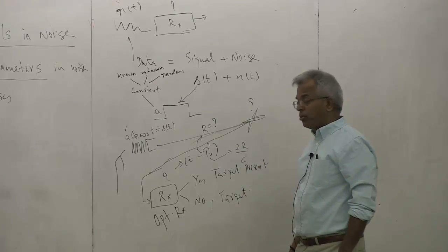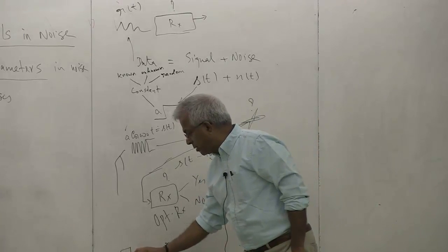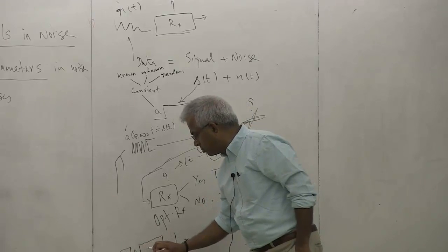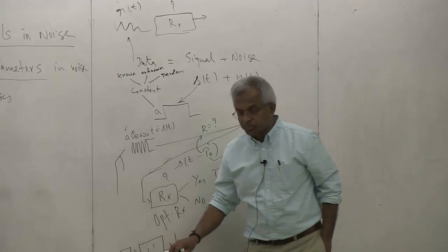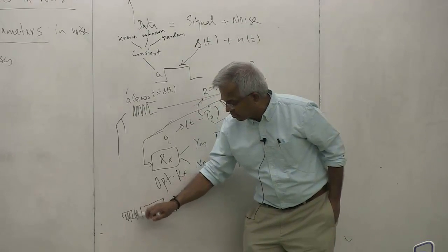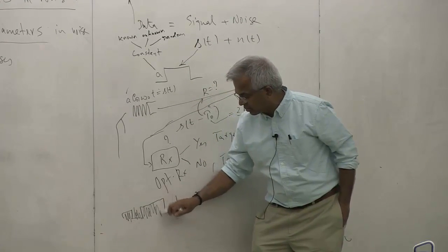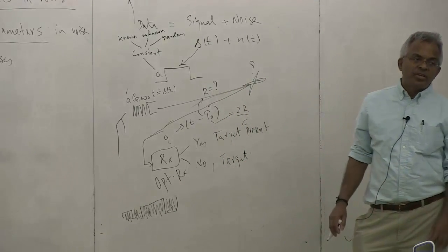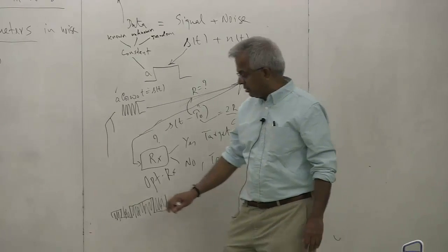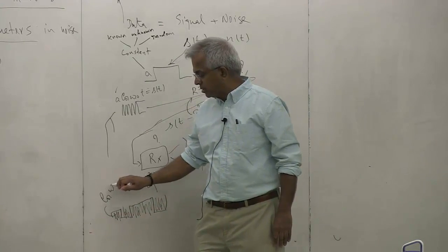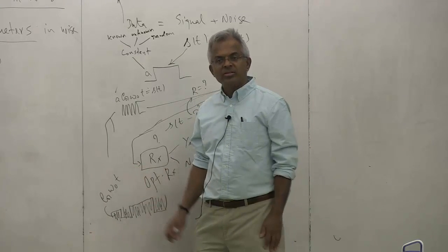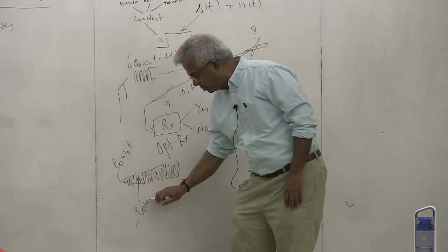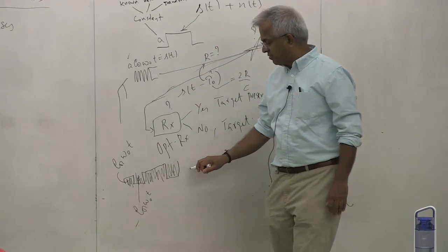So it is the same thing in communication. Even if you are transmitting 1s and 0s in some fashion, say 1 0 1 1 0, you don't transmit like this, you actually modulate it by some carrier, depending on the transmission scheme. If it is PSK, phase shift keying, to transmit one, let's say you use a pulse of cos omega naught t, and for minus 1 you use minus cos omega naught t. So this is phase shift keying.